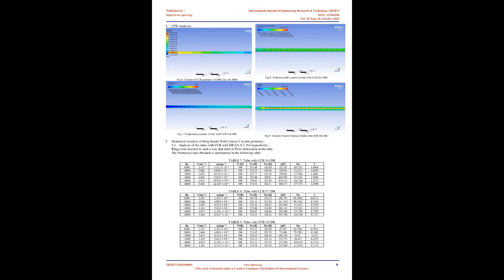6. Numerical analysis. 1. Grid dependency. Grid independence test. A solution refinement method is used. By using solution adaptive refinement, cells can be added where they are needed in the mesh, thus enabling the features of the flow field to be better resolved. When adaptation is used properly, the resulting mesh is optimal for the flow solution because the solution is used to determine where more cells are needed.